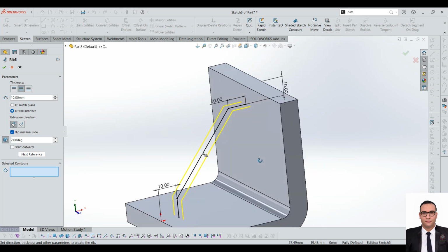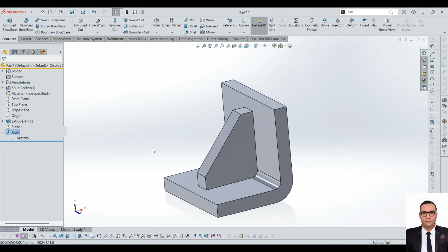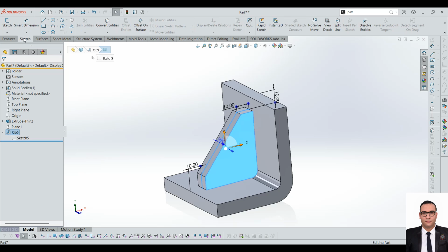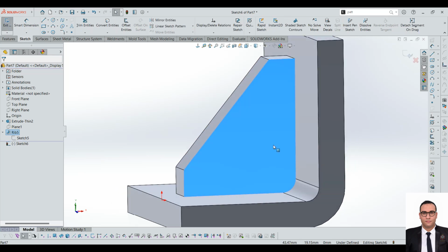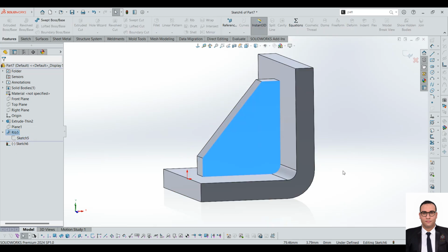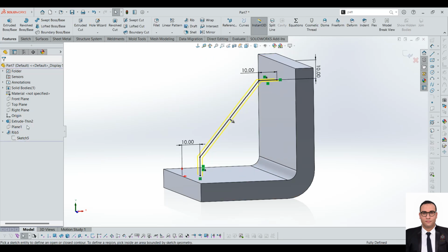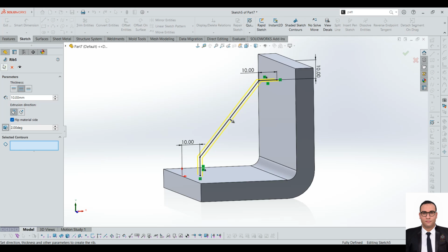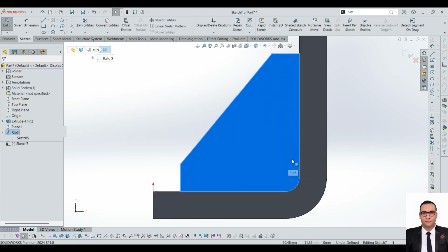Okay, that's the problem. Normally people do this shape when they work with the rib in real life. They cut it here. Let's try cutting it. Let's remove the draft first, because as you see, we have an angle here. In order for us to cut it, we have to make it simple. Okay, first let's do this one.